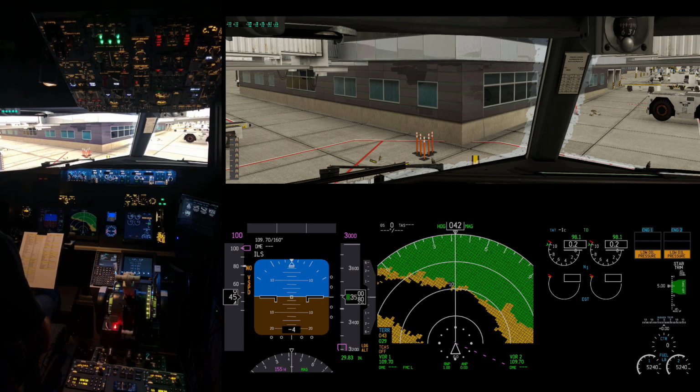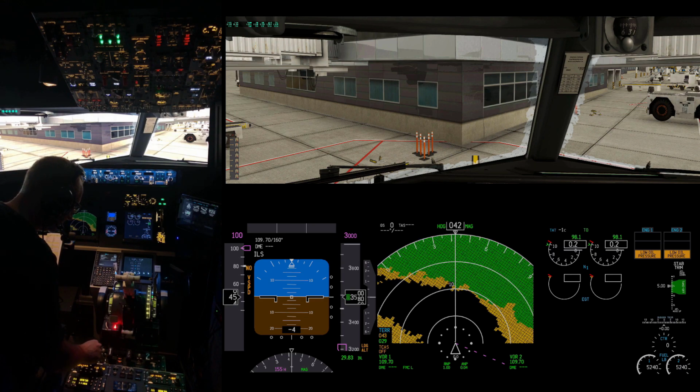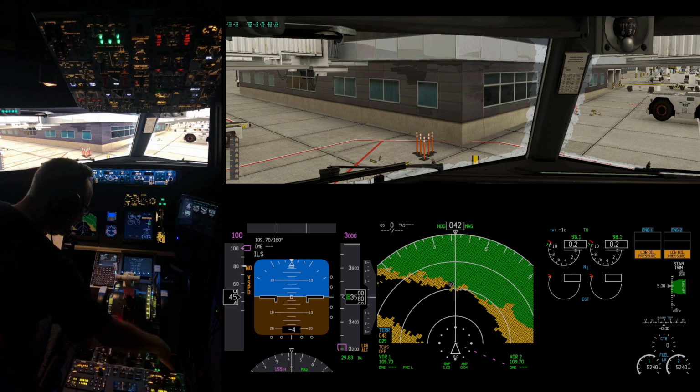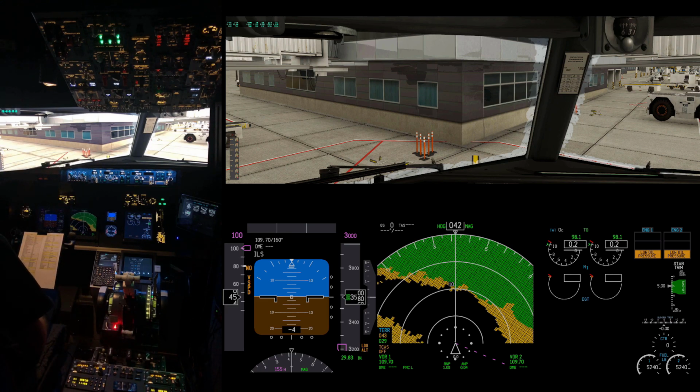We checked our aircraft documentation. We're good, and we're good on checking any master cautions. So first of all, we now need to check the engine fire instrument. So we'll do the fire test, the fault test, the fire test, all good. We'll check the squibs. The squibs are 3 green, so that's all good.